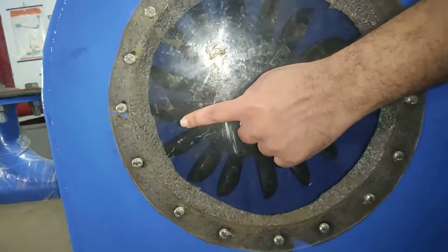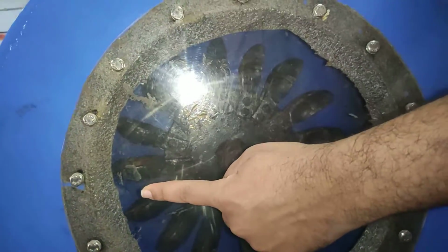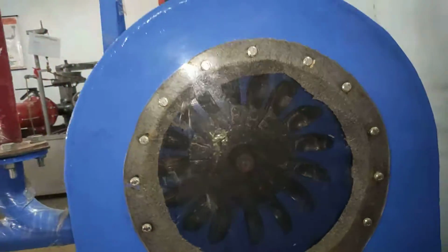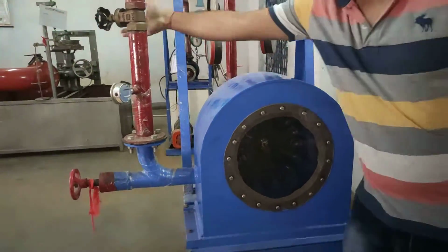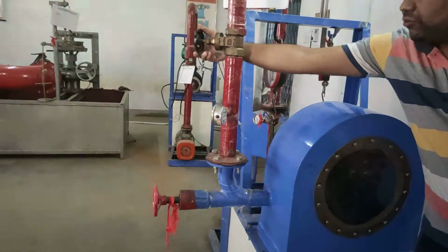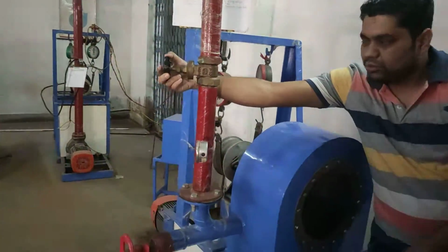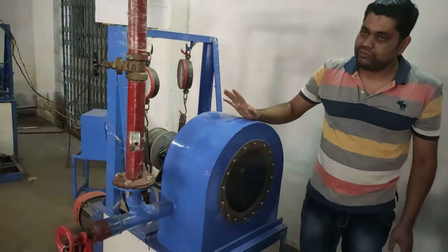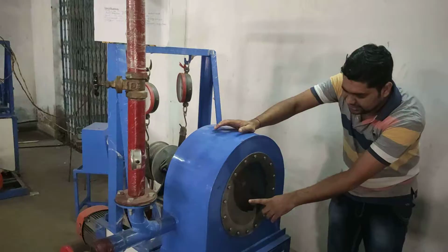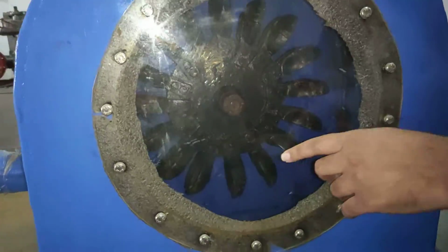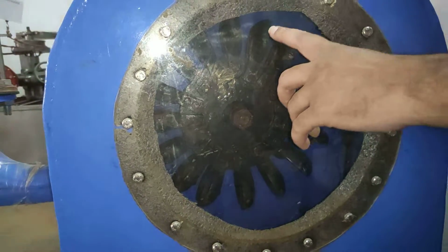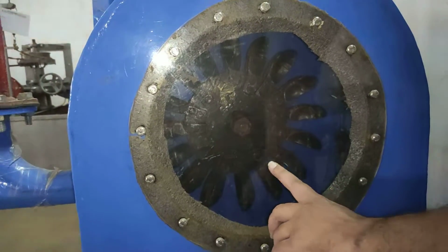In other turbines or test rigs there is a movable nozzle, but here it is a fixed nozzle. So this is the fixed type of nozzle, and the flow should be controlled through this orifice meter. What amount of flow will occur through this orifice meter, you can control the flow, and the nozzle section should be fixed here. So here are your buckets. Coming close. So here are your buckets. There are 18 buckets. Let's count it. It will be 18.